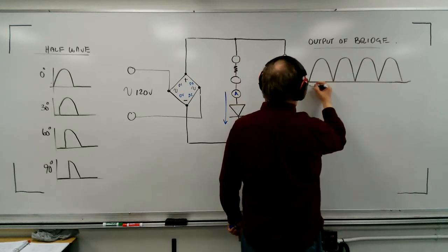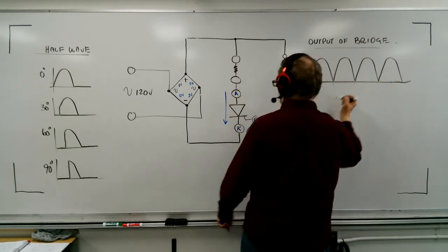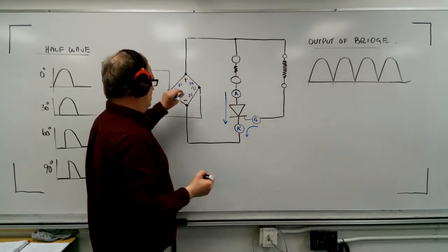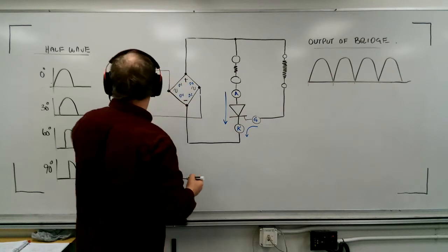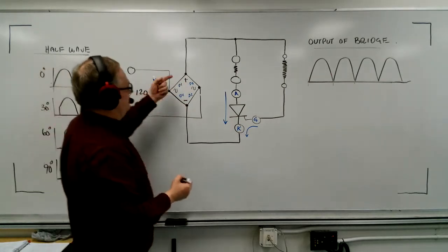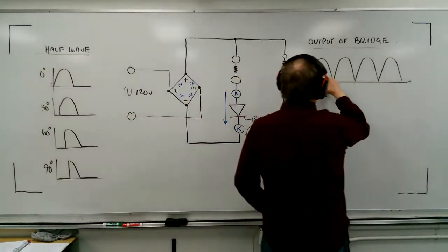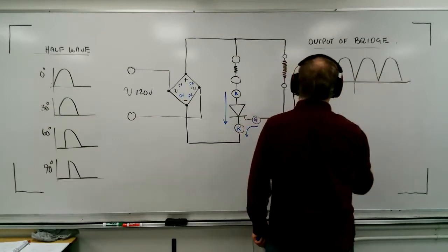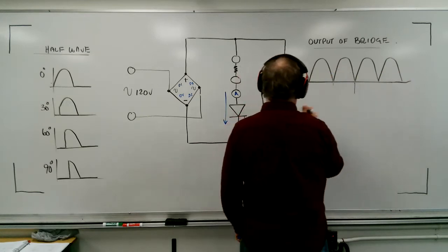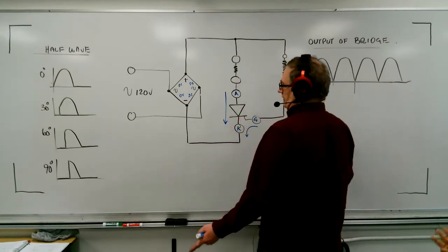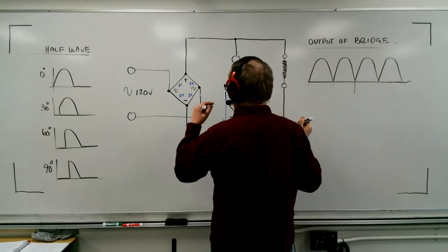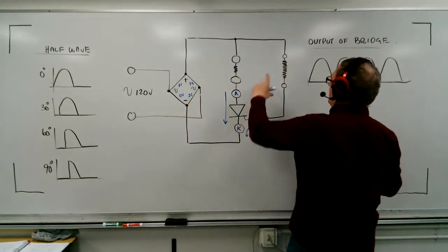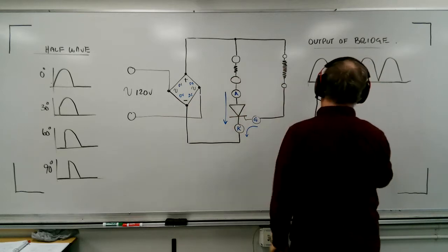So that means we get one alternation, and then we get the second alternation, because what these diodes do is they flip over this negative alternation and feed it in as though it was positive. So this is 2 cycles here, and we see actually 4 ripples, so 2 ripples per cycle. Now, if we were to control this with an SCR, so now we look and see we have an SCR in here. So what voltage will the load possibly see?